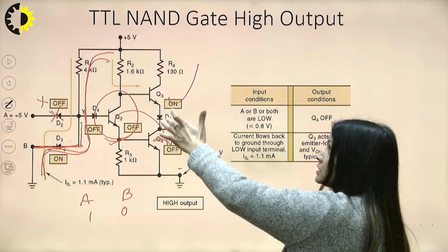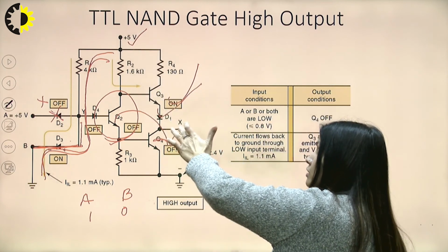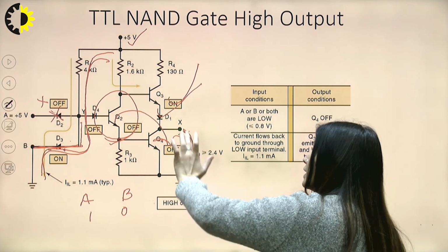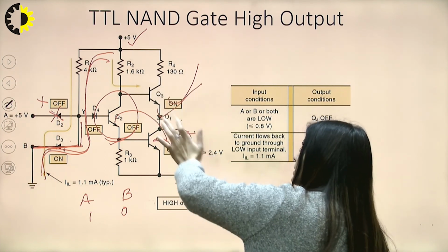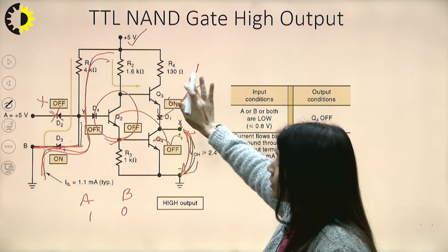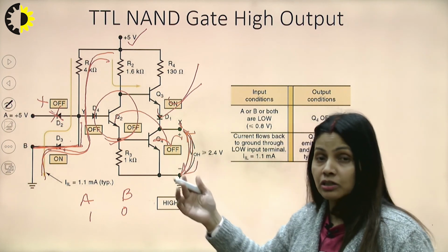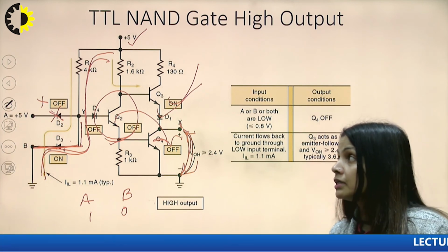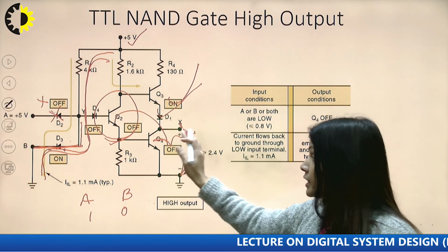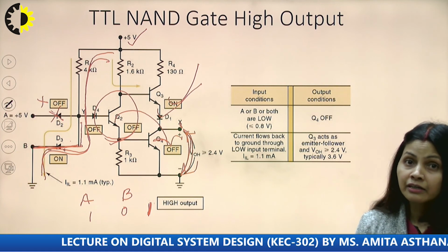whenever we analyze this voltage, this is at plus 5 volts, this is a conducting transistor, and some voltage would be there. Taking this reference between these two points, the voltage drop will be high as this transistor is conducting, and we are getting some voltage which is above the output high range. As I told you, the output voltage for the output window must be greater than 2.7 volts. So this must be on, and hence we are getting logic 1 as output. This again verifies the NAND gate.